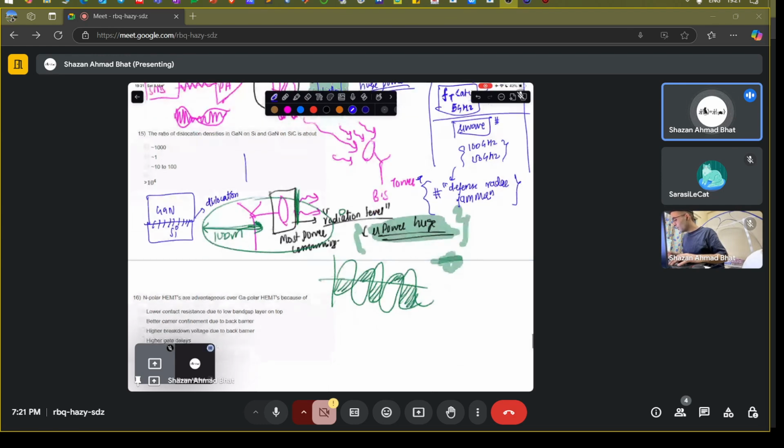What you can do is use an aluminum nitride nucleation layer and then use silicon. This will reduce the mismatch. And then you can use gallium nitride, or you can use a silicon carbide interface. These are some of the options for using the substrate. But mostly there are huge dislocation densities because of lattice mismatch at this particular position.